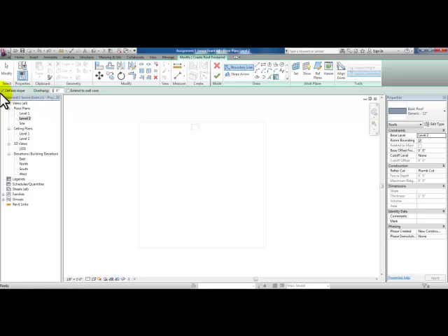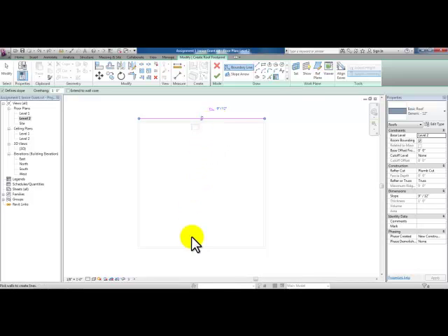And then with the check mark in define slopes, we'll go close to the top wall and see that there's a dashed line that represents the overhang, and then left click, and the triangle shows me that it is going to be a sloped roof coming down towards this wall.